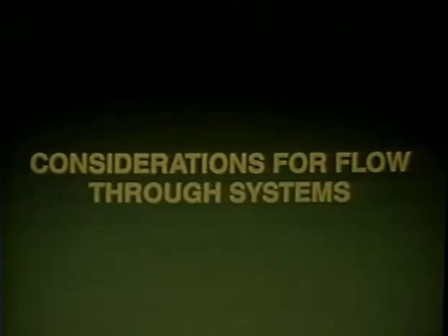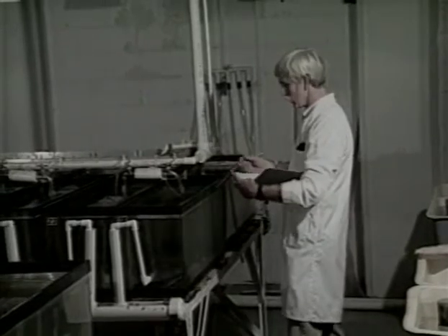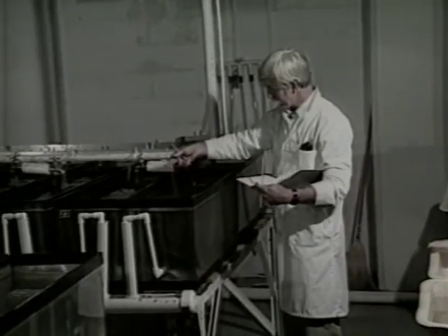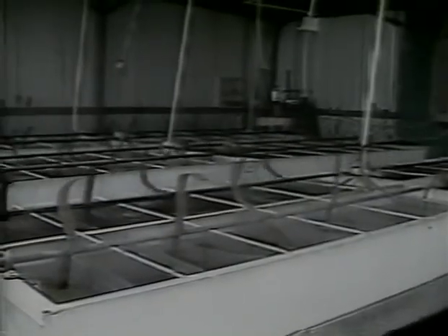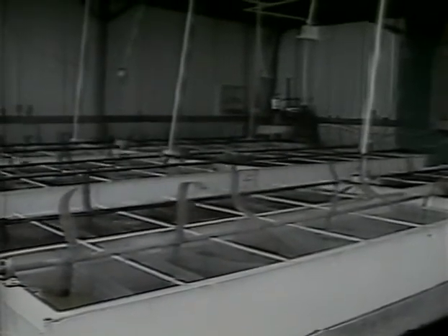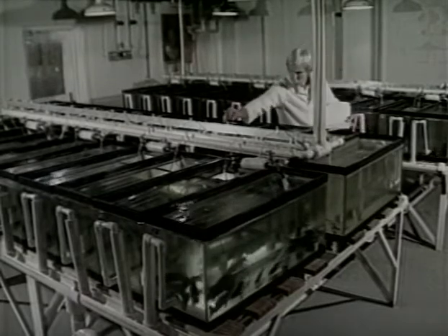Considerations for flow-through systems. Water quality in flow-through systems such as holding troughs is dependent on the quality of the source. Minimum total alkalinity and total hardness are usually adequate since most producers do not hold fish for extended periods of time. Sufficient oxygen may be maintained through the use of air blowers or bottled oxygen. By spraying incoming water through valves, carbon dioxide is liberated and additional aeration is achieved. Problems with hydrogen sulfide and other compounds such as iron may be removed by aeration. However, more sophisticated measures may have to be taken in some cases.